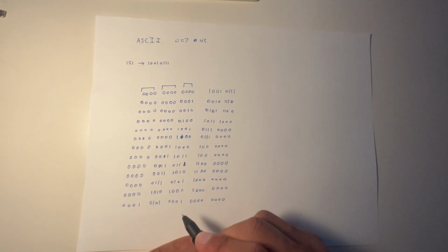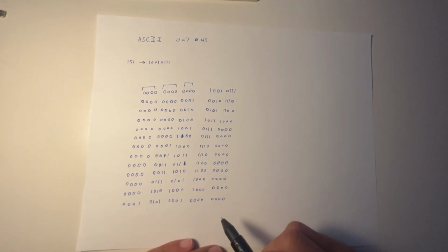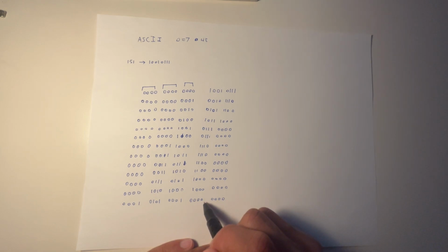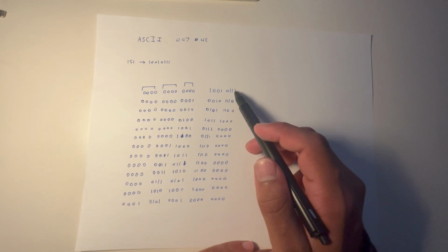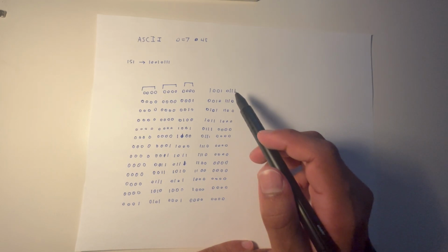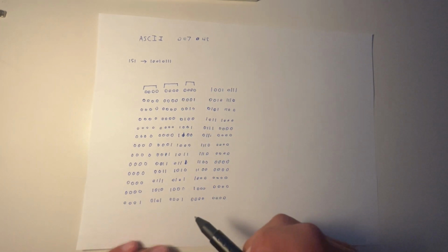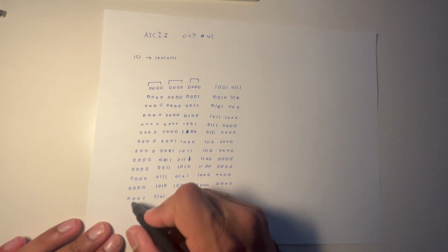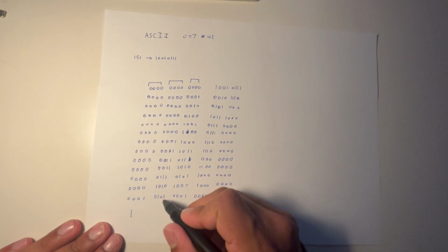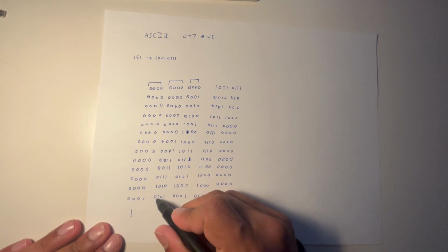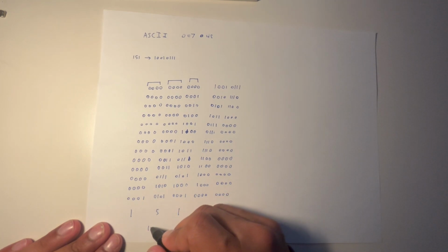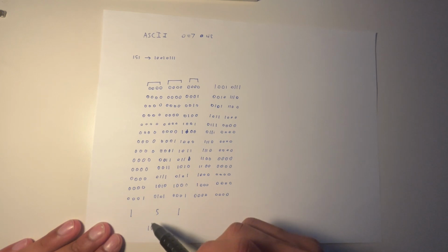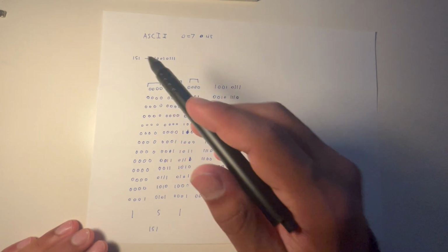Okay, so after that lengthy conversion, we can now see that all the 1s have been moved to the left, and we started with a 1 in the least significant bit, so that means we're done because we've shifted it 8 times. Now if we read each nibble, we have 1, 1 plus 0 plus 4, which is 5, and another 1. If we put those together, we have 151, which was our original input, so we did that right.